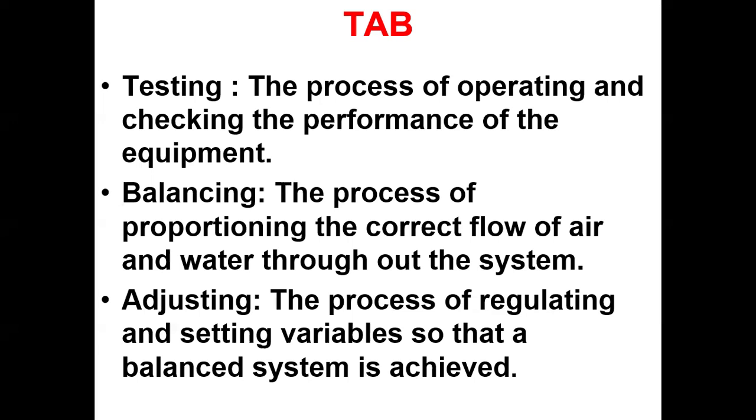So you need to initially control the air coming out of the machine itself. How? By placing a VCD, a motorized volume control damper, at the entrance of the duct, which is the starting point of the duct. Then you can control the air. At the same time, for each room's requirements, you can adjust the VCDs. We learned that whenever a branch duct is splitting, especially from a Y-piece connection, you must implement VCDs, especially at the outlets. Once these outlets are set to certain angles, with the help of an anemometer, which is used to know the velocity of air.